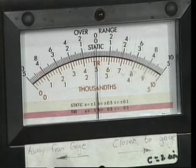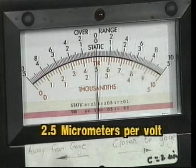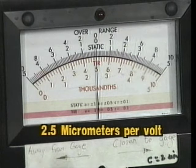The separation changes can be read from the analog display, or as we will demonstrate in this experiment, can be recorded as analog signal voltages. Signal voltage range is plus or minus 10 volts. At 2.5 micrometers per volt, this equates to a measurement range of 50 micrometers, which is more than adequate for our experiment.